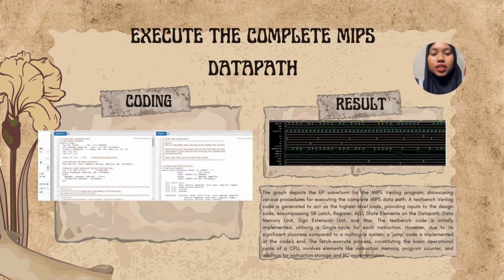The graph depicts the waveform for the MIPS Verilog program, showcasing various procedures for executing the complete MIPS data path. A test bench Verilog code is generated to act as the highest level code, providing inputs to the design code, encompassing SR latch register, ALU, state elements and the data path, and data memory unit, sign extension unit, and MIPS. The test bench code is initially implemented utilizing a single cycle for each instruction.